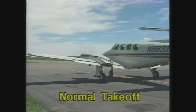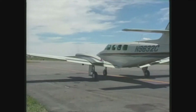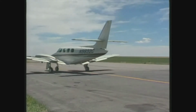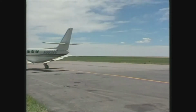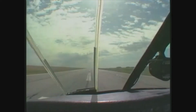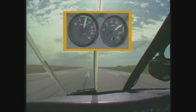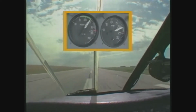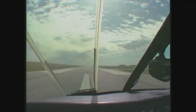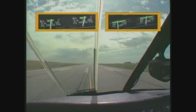For a normal takeoff, you should set the flaps according to the manufacturer's recommendations. Front range traffic, Crusader 90832 Charlie, departing runway 26 at front range. Apply power evenly to both engines and watch for any directional control problem which may indicate uneven engine acceleration. Once you have full power, check all the engine gauges to make sure both engines are operating properly.